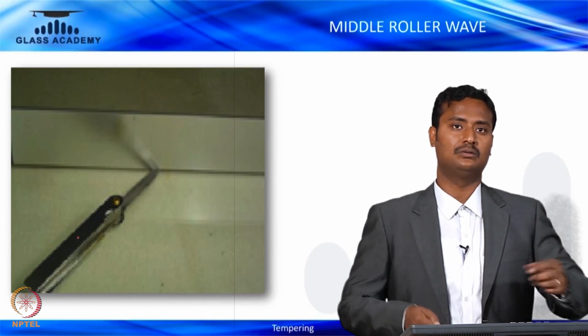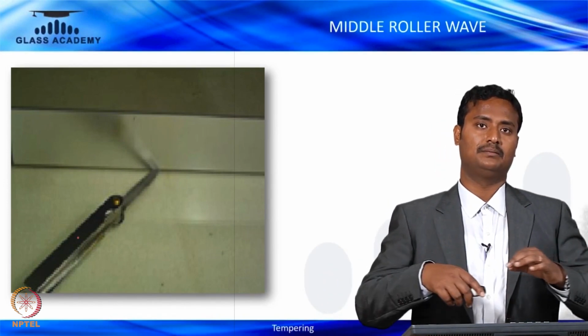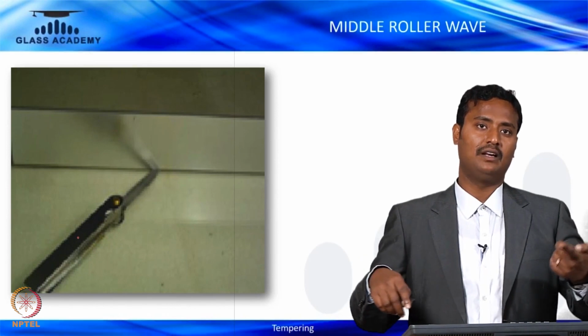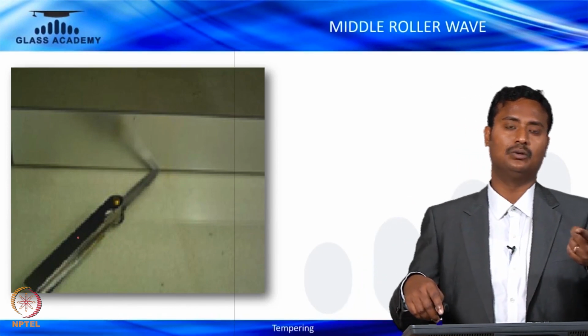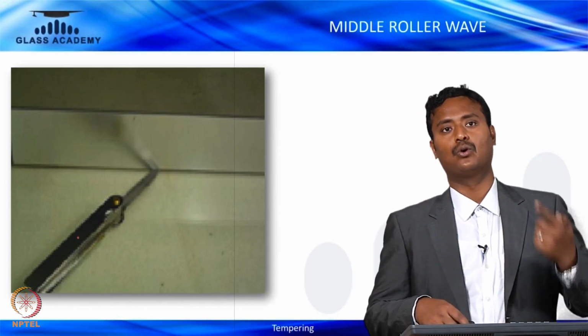If you're not able to keep it straight, the flatness gauge or the feeler gauge, either of these can help us identify how much overall bow and local bow is there.